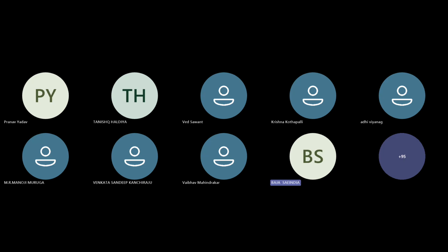In that folder, you can find an SKC file which has all the log values mentioning the travel of your wheel with respect to a bump or a drop, with some force analysis as well. You need to import that into your project folder as described in the CarMaker guidelines, rename it, and load it into the IPG kinematics section.